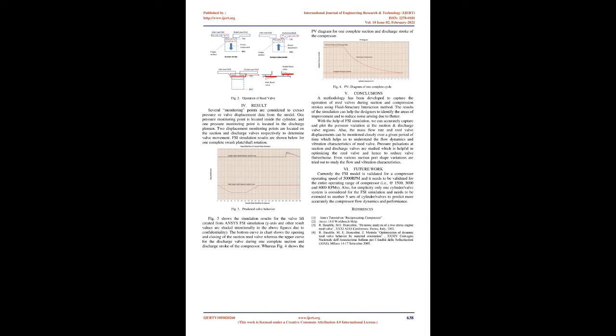Result. Several monitoring points are considered to extract pressure or valve displacement data from the model. One pressure monitoring point is located inside the cylinder, and one pressure monitoring point is located in the discharge plenum. Two displacement monitoring points are located on the suction and discharge valves respectively to determine valve movement. FSI simulation results are shown below for one complete swash plate/shaft rotation.